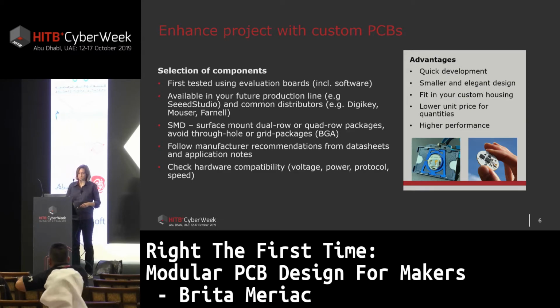And for the first prototype, it is good advice to stick with the components from your evaluation boards, but in different packages that are available from your distributor, from your production lines. And many component manufacturers provide a lot of recommendations about how to implement their products. And if you can't find this in a data sheet, it will definitely be in an application note.